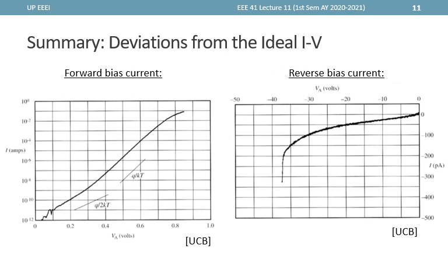And that is actually depicted by these two plots right here. At the reverse bias case, the current does not actually saturate, but increases slightly because of the additional current from the carriers generated and eventually drifting through the depletion region. Now, why is the current continuously increasing?